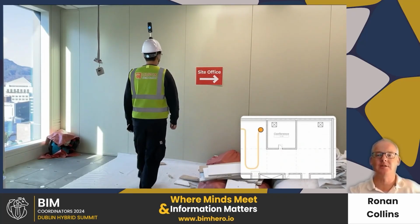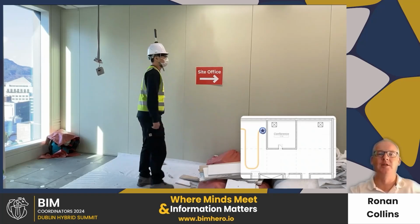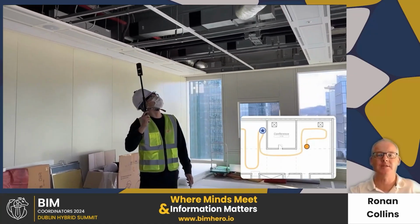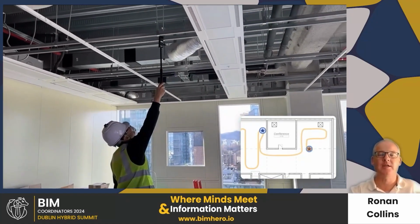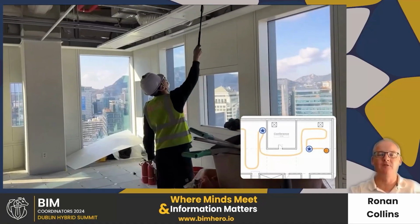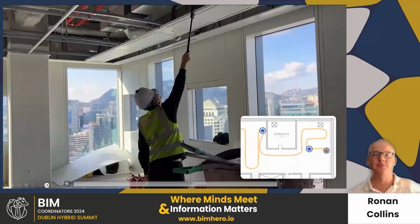The recommendation is to walk around as if you're guiding your auntie or your granny around. So don't walk too fast, but just walk fast enough that you can cover the area. And the camera is capturing all of the site in 360. So it's basically creating a series of snapshots through a video. You can put the camera on a selfie stick and you can extend the camera into MEP spaces. So it's a good way of capturing areas that are not easily accessible. And I've been doing that on a project at the moment, getting about 4 meters, 5 meters up into the air into really confined spaces. So this is a really good way of capturing the site.